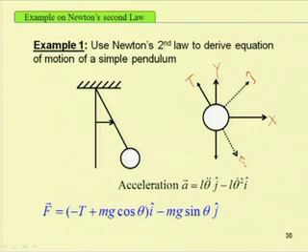This is the free body diagram of the bob, in which the physical coordinate system can be shown either in terms of x y or using another coordinate system in terms of unit vectors i and j. The total force acting on the system can be written. This is the tension force T, and another force acting on the system is mg. Under the action of these two forces, the system will be in equilibrium if we add the inertia force to the system.